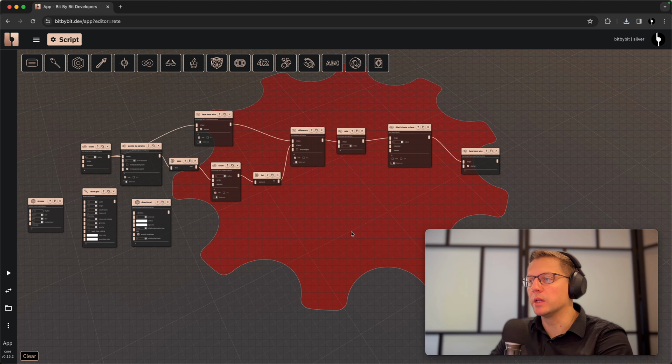So you see that we still have this in the middle, and that just requires me to increase the radius a little, and now it's gone. So now I have the inner hole on that face, and I will just hide this. I will hide this, and that's it. So now it looks quite okay. This is what I want to extrude.